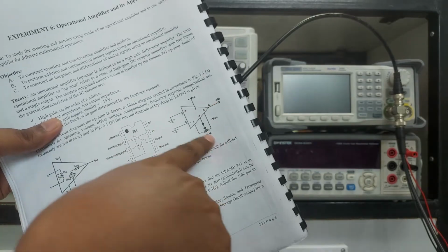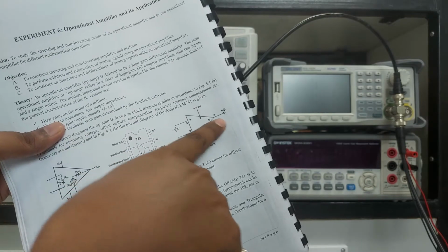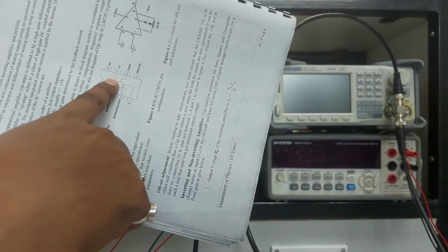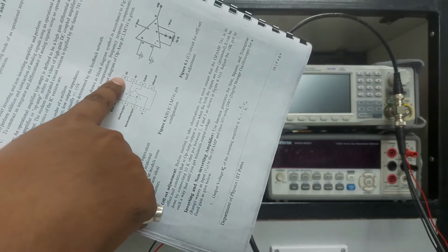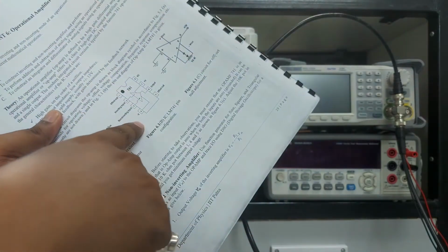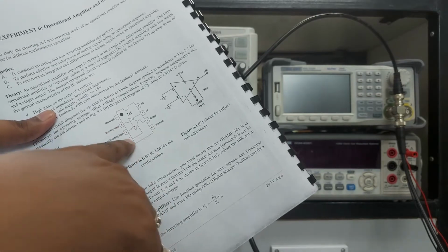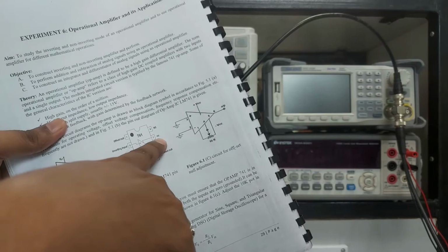We are representing it by the triangular shape. So 2 and 3 are for the inputs and 6 is for the output, and pin 7 is the plus VCC, or plus V voltage, and pin 8 is not connected. We're not going to use this pin throughout the experiment. So there are 2 pins for the offset, one is for the negative voltage, 2 is the input, 6 is the output, 7 is the plus V.